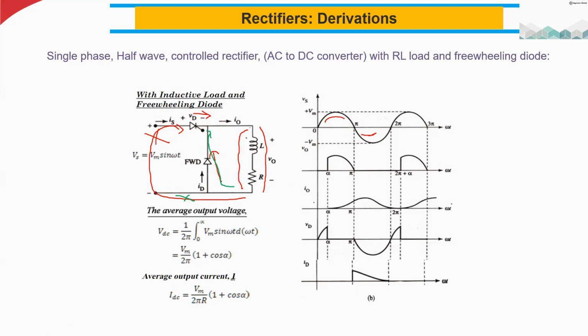So in this case, we will not have this beta anymore. This is the output voltage. We are supposed to get this, somewhere here, up to beta conduction. Because of this flywheel diode, the flywheel diode just bypasses the magnetic field energy and avoids this negative conduction. That is the use of this flywheel diode.